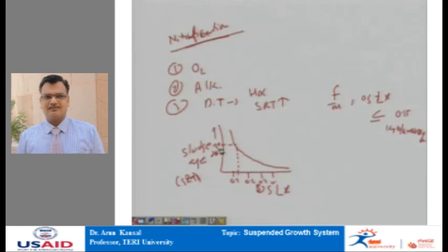Normally, the generation time of nitrifiers is also temperature dependent. At 10 degrees centigrade, the generation time is approximately 3.4 days. At 20 degrees centigrade, it is approximately 1.32 days. At 30 degrees centigrade, it is approximately 0.53 days. So, as the temperature increases, the generation time reduces, and that is why nitrification occurs more often in summer conditions. And since the wastewater gets nitrified, we have the rising sludge problem in the secondary settling tank more during the summer. This is the reason I mentioned it in the last lecture when I discussed the rising sludge problem.